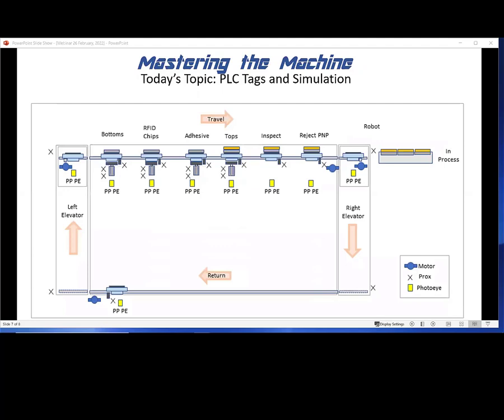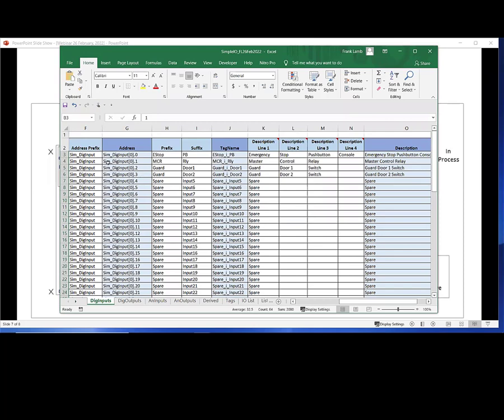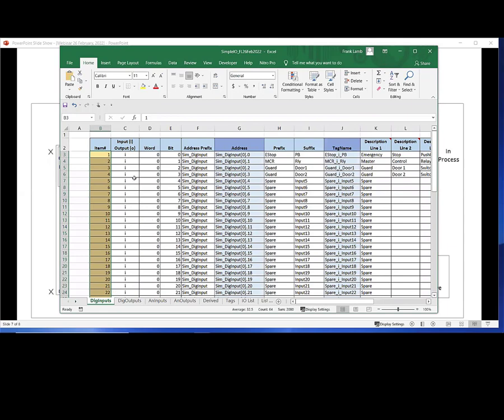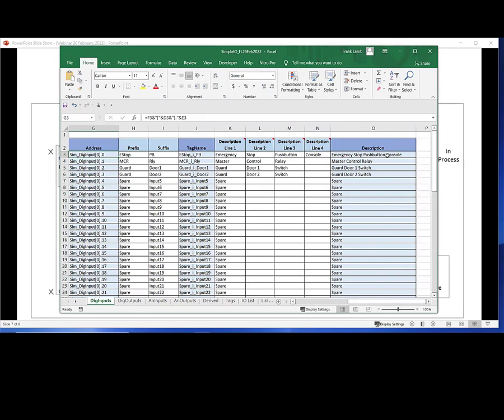So what I do is I give them this spreadsheet. Now this spreadsheet, you could create pretty easily yourself. What I do here is I use in Excel what would be called, I suppose, concatenation. If I go to this tag, this is made from F3 and, putting this format in here, and E3, and I create the alias for the tag and the tag name itself, right? And you can see this here, and then I create a description.